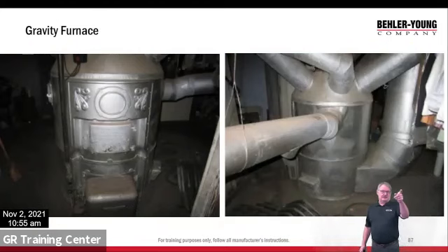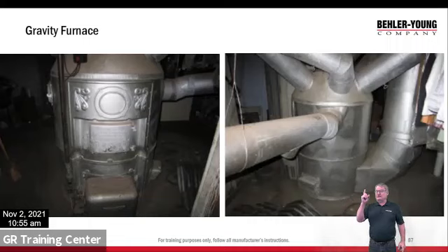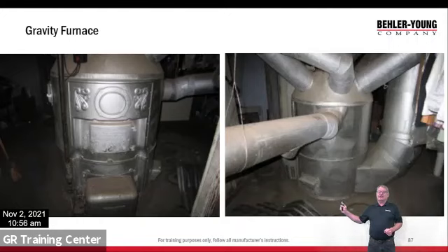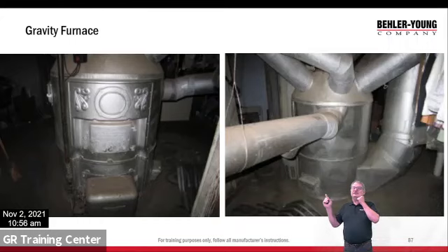If I look over there, you're going to see I've got a fire door. That's where I stoked my coal. And over here, you can see the sheet metal jacket with this huge ductwork coming off of it. Right here, this big pipe is the cold air return. Cold air naturally falls, and all the pipes are on a diagonal because heat rises. So the heat just naturally rose to heat the space, and the cold air would fall back in this return. This little guy here, that's a humidifier. It's just a little spot to put water. This is the flue pipe right here.